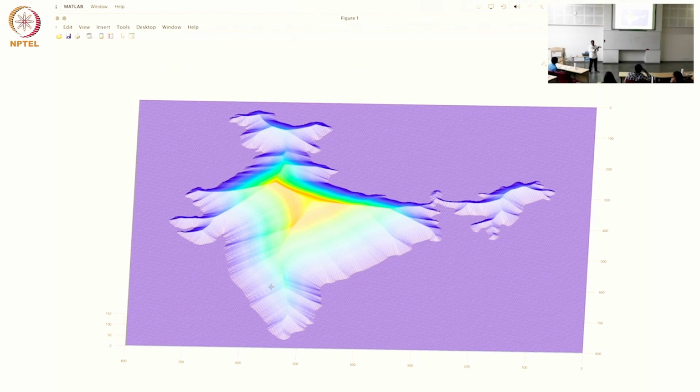Or I could have a slope downward that takes you back to Delhi, for example. You're coming back from Shimla or somewhere, it takes you back. By the way, the slopes on these roads are usually kept fixed. So these roads on mountains usually have fixed slope, so that the rider, the car, doesn't experience ups and downs too much. But along a stretch, the slope would usually be constant, right? The consequence of keeping constant slope and a low slope is that the road will become very long. If you keep the slope high, then you have a shorter trip, but it's going to be tiresome.